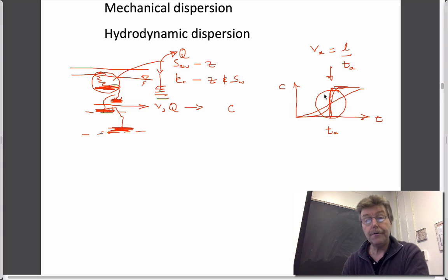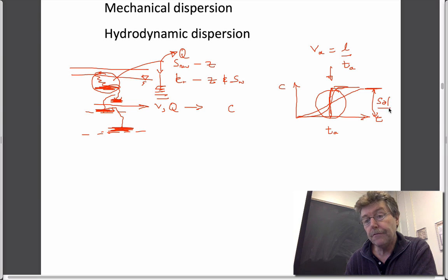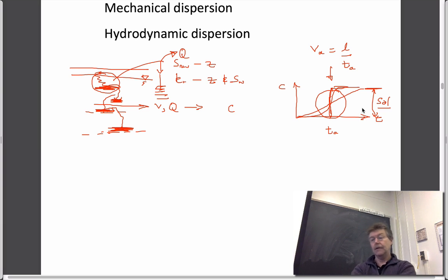We'd also like to know whether when it arrives, it really arrives at the concentration that we think it is from the upstream, which we've called the solubility limit before. We've defined the solubility of these components. It's 1100 parts per million, or 1100 milligrams per liter, for TCE. And that's the maximum amount that can be held in water at equilibrium. Can't get more than that, could be less than that.